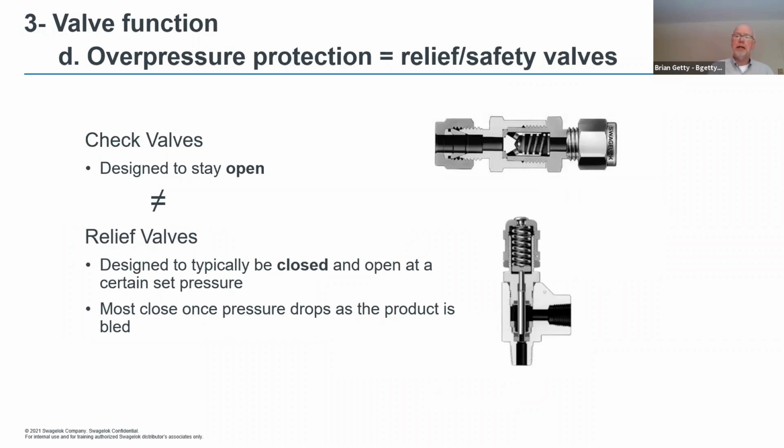Okay, the difference between relief valves and check valves. Because I've got customers who say, "Oh, Brian, I need an overpressure protection of 25 psi." And as you saw in the previous slide, you can have 25 psi opening pressure. Problem with that, check valves, when they are functioning in a normal system, are actually meant to be open. Okay, they're not meant to be closed, they're meant to be open.